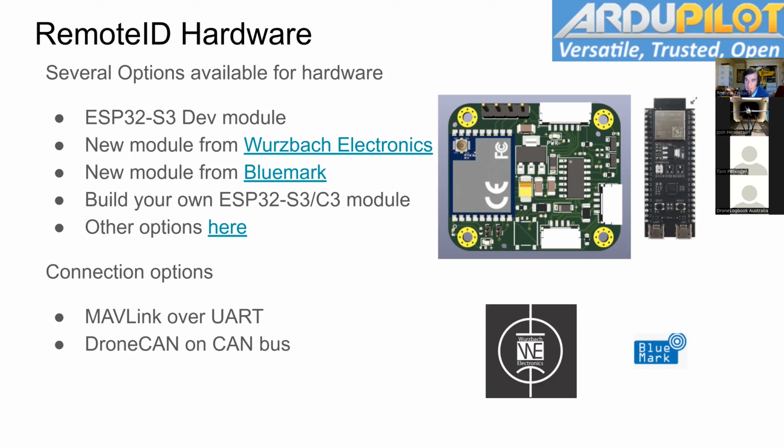Normally the second one is used for flashing, and the primary is a Silicon Labs USB serial adapter built into the dev board. I could trivially modify the firmware so that the USB port does the MAVLink, and you could probably then plug that straight into your companion computer and be good to go. Oh yeah, that'd probably be useful.